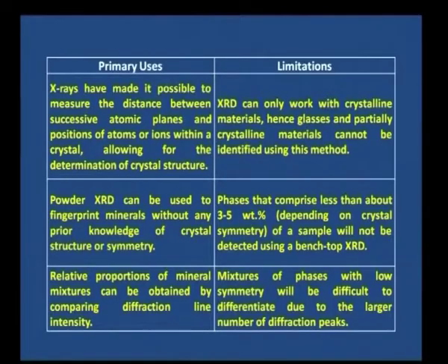XRD, that means X-ray diffraction, can only work with crystalline materials, not non-crystalline or amorphous ones. For glasses, you cannot use X-ray diffraction, because the atoms are not arranged in a periodic manner. The atoms should be arranged in a periodic manner, then only X-ray diffraction can be used. So, that is one of the limitations. Okay. Powder XRD, which we will be dealing with in a moment.